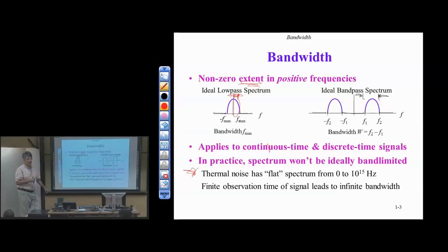We do communications with sampling and discrete time work up through about 64 gigahertz because there's an open ISM band between 57 and 64 gigahertz. There's some optical communications that goes to higher rates, but for electronic sampling, we're below 64 gigahertz. So the whole spectrum we care about is flat. We've got basically thermal noise equally present at all frequencies.